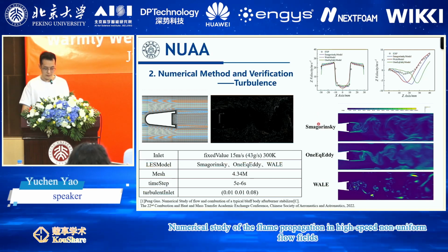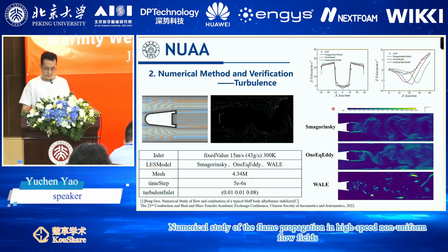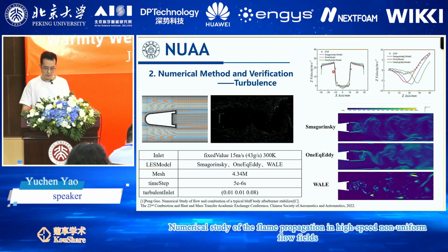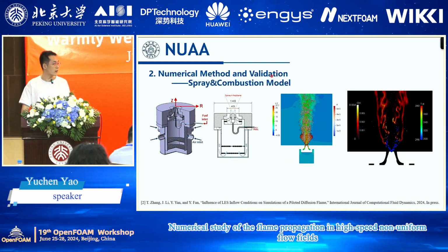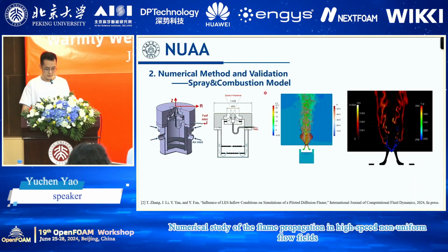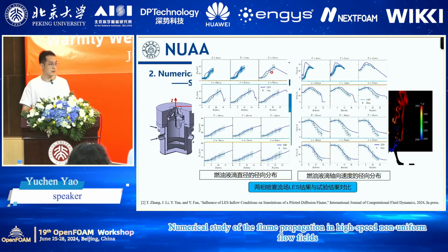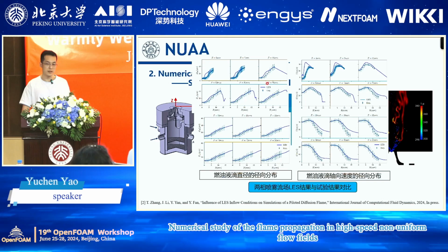We've compared the Smagorinsky, one-equation eddy viscosity and the WALE models, and found out that the WALE model has the best performance. The spray and combustion model has been verified in our previous work, and the simulation results have a great fit with the experiment data.